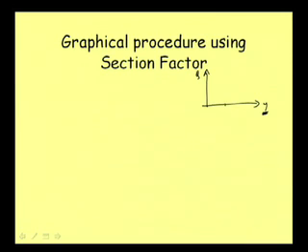Suppose for this arbitrarily chosen y value we get this Q value. We know that this is not our Q, but putting some y value we get a Q value. For another y value, we get another Q value. Again, let me try another y value, and we get another Q value. We should be careful that our required Q is somewhere here, Q required.